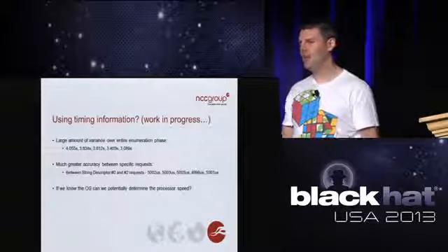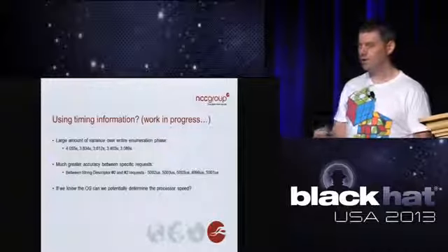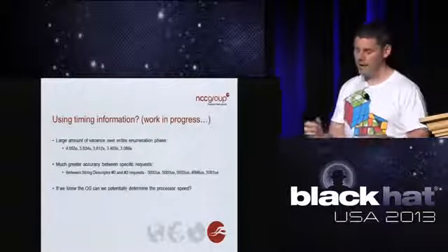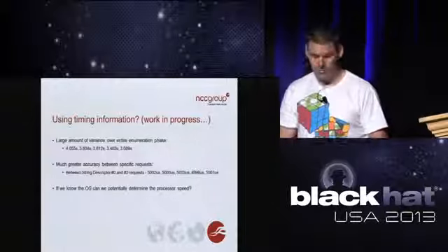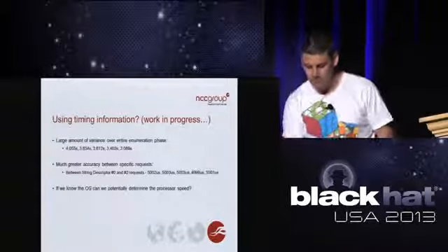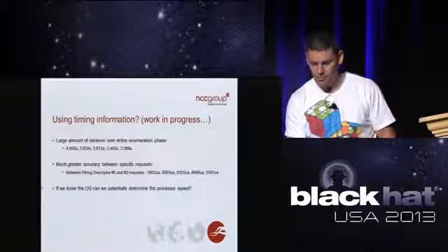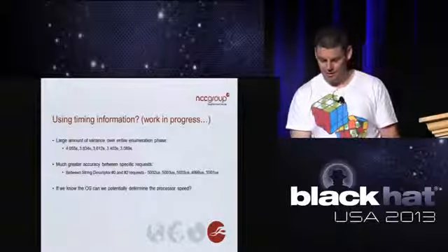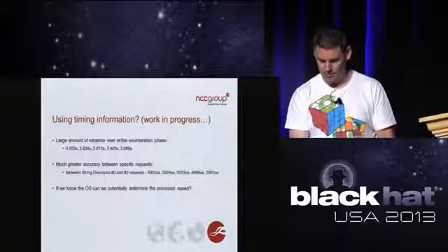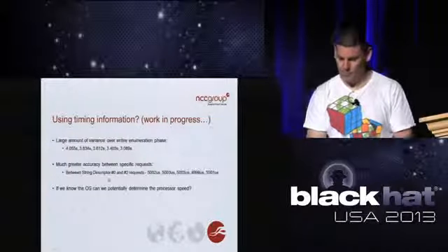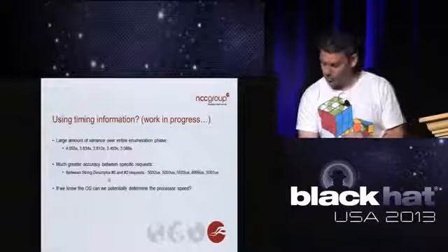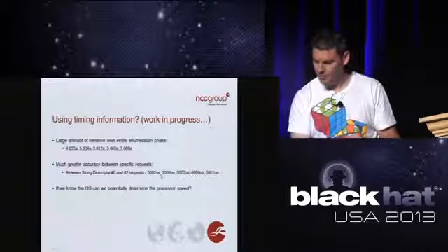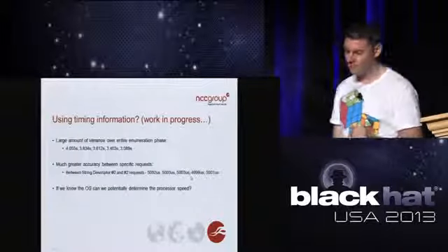It typically takes around 5 or 6 seconds to go from initial device insertion to the point where class-specific communications are occurring. But if you tie it down to the timing between specific elements within that enumeration phase, so here I've looked at the difference between the timing of request for string descriptor 0 and string descriptor 2, you're talking of a difference of 1 or 2 microseconds.